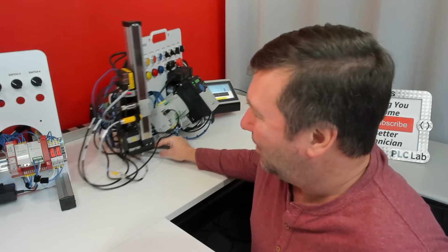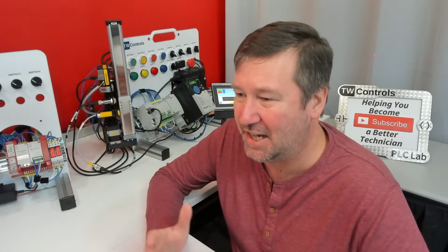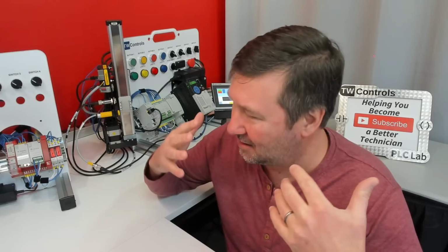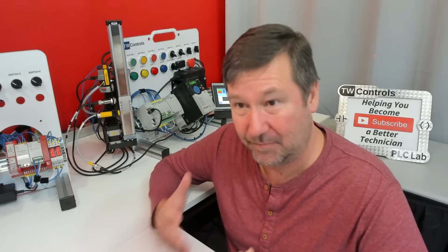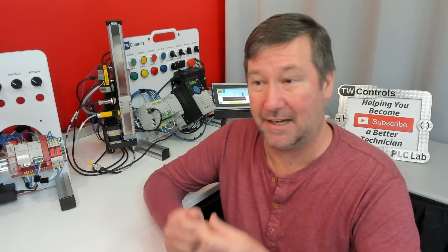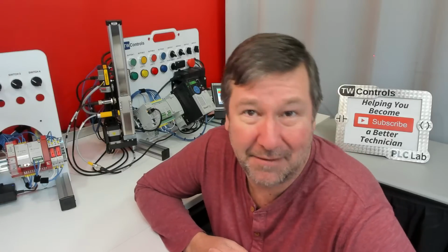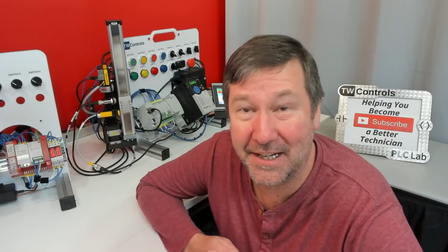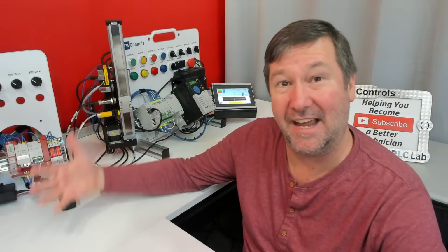So which one is the best is still a tough question; it's more application dependent. But I always say the more we can minimize the wiring, the better we're going to be, longevity wise. We're going to be better building equipment because, on average, it takes 4 minutes to wire. By the time you cut the wire, strip the wire, ferrule the wire, print the wire label, put the label on, do all the things, people average 4 minutes. So every wire you can eliminate, you're saving 4 minutes. And as the machine ages or is having issues, there's one less wire that we have to troubleshoot.